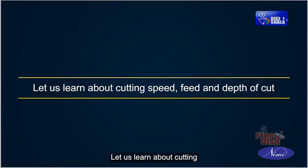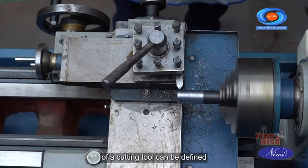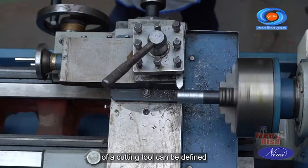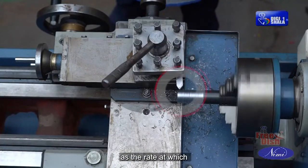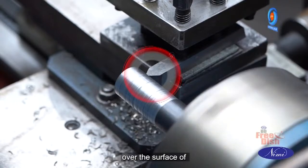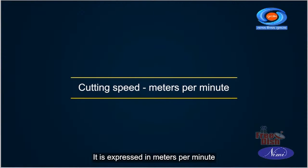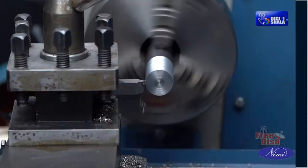Let us learn about cutting speed, feed and depth of cut. The cutting speed of a cutting tool can be defined as the rate at which its cutting edge passes over the surface of the workpiece in unit time. It is expressed in meters per minute.